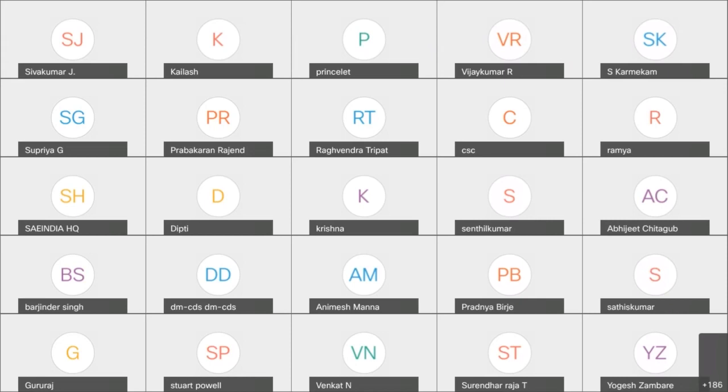It's a good question. In 2011, there was not much explanation in the standard, but in 2018, they have given a very elaborated way. The DFA has to be performed at various levels: system level, hardware level, and software level. At each level, you need to look at it with the perception of common cause failure and cascading failure. The input would be the FMEA or FTA, from which you can pick the initiator, meaning the common cause initiator. Based on that you can do the analysis, which should address the common cause and cascading failure aspects.